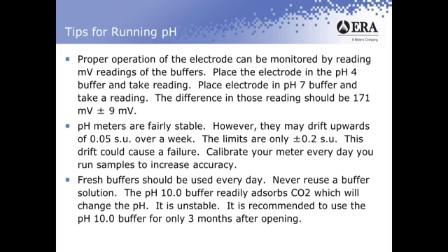I would also recommend that you tighten your dynamic range as much as you can with respect to running your pH meter. What you need to remember is that you've got to bracket your calibration standards around the expected value of pH. So generally you calibrate with 3 buffers, a pH 4, a pH 7, and a pH 10.